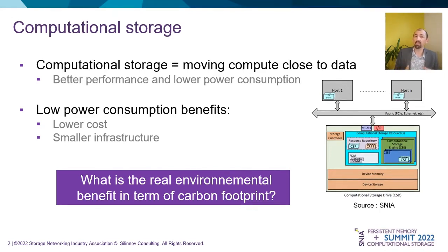That leads to multiple benefits, where the two most important are better performance and a lower power consumption. Better performance because you save time in the whole processing task. The SSD controller processes directly the data from the NAND flash. Lower power consumption. Moving data is not energy free. Moving data may represent a huge percentage of the total energy in a standard system.